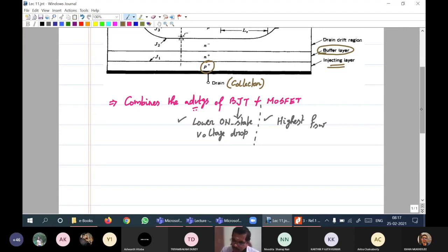Of course, the symbol is quite simple, no? Therefore, I will complete that. I'll draw the symbol first. See, it is insulated gate bipolar transistor. So the transistor will have collector and emitter terminals. This is the collector, and obviously this is the emitter terminal. But then you need to understand that the gate is insulated. Therefore, have a space, allow some gap between the collector and emitter layer, and this forms the N-channel IGBT: gate, collector, and emitter. This is one symbol.